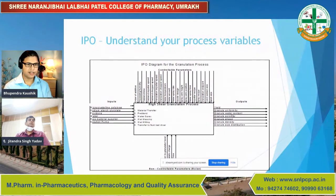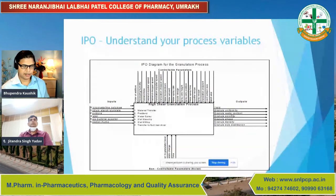In order to measure that it is consistent, you can look at certain attributes like density, shape, particle size distribution, porosity, water content, things like that. And why do we measure these things? Because you want to ensure that every batch you're manufacturing is consistent, is going to be manufactured according to the process we registered, and in accordance with the batch manufacturing record you gave to an operator. Also, these are the things that affect or can affect the product quality, so obviously you want to have a certain degree of control.